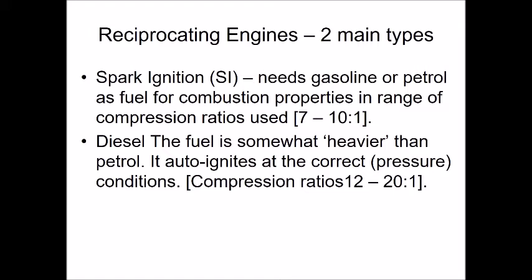So spark ignition engines use gasoline. That's what they burn. Now they tend to use something called a spark plug to initiate combustion, and we're going to see something about that in subsequent lectures. And they have compression ratios which are in the range of between 7:1 and 10:1.